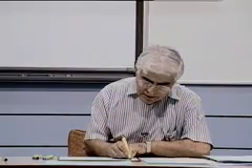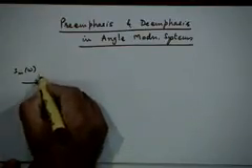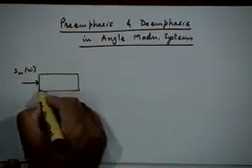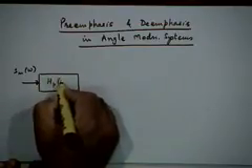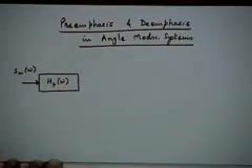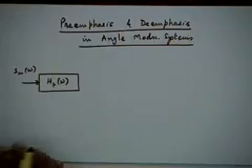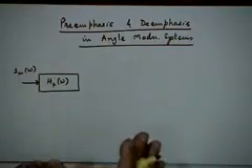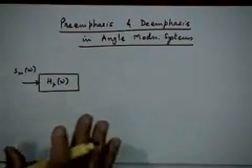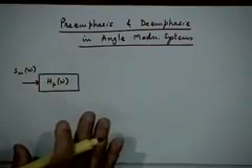In the baseband system, you have your message signal coming in, which has a power spectrum of S_m(omega). Before you transmit it, you pass it through some filtering. This filtering will modify the spectrum of the signal, and therefore in that sense it will distort the signal also.